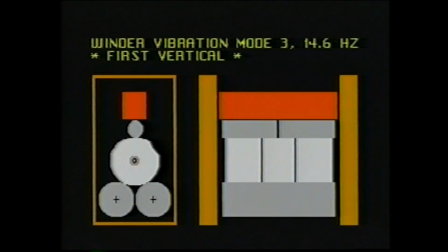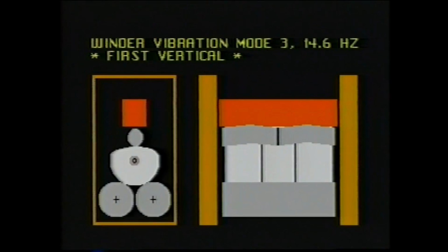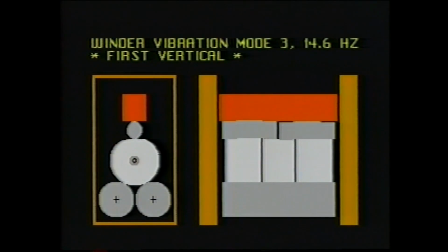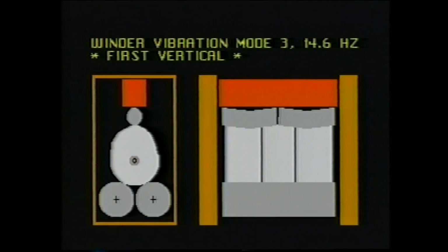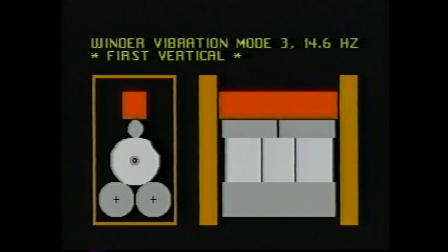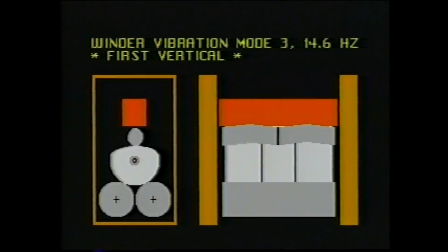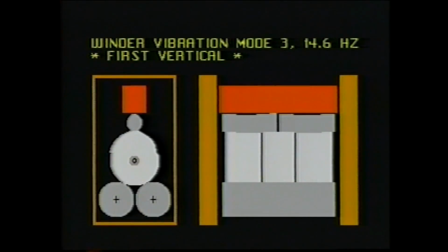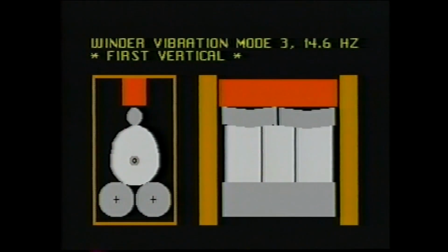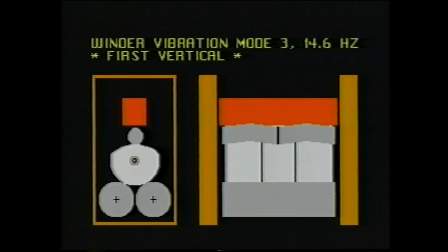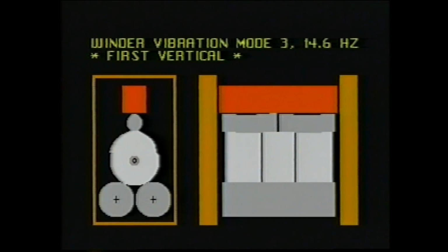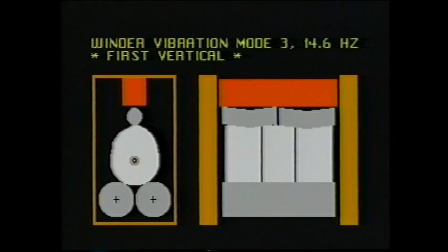Vibration starts as an audible rumble at small rewound diameters during acceleration. The vertical motion of the rider roll may develop such that the rider roll lifts off the set and the paper rolls are thrown from the winder. Attempts to reduce the severity of this mode by increasing the rider roll stiffness by using direct acting cylinders can improve the situation somewhat. Attempts to reduce severity of this mode by various damping mechanisms, including friction and tuned dynamic dampers, have met with little success. A total solution to this problem mode remains undiscovered.